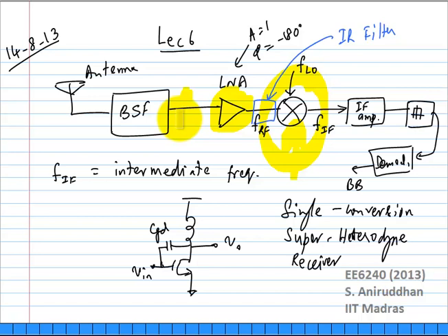Okay. Many of them will not even be applicable here. There will be fundamental trade-offs between power, number of bits and so on. For example, is it possible to use a Delta Sigma ADC here? A Delta Sigma ADC fundamentally requires oversampling. If you're at RF, then you really need to oversample it at a very high frequency.